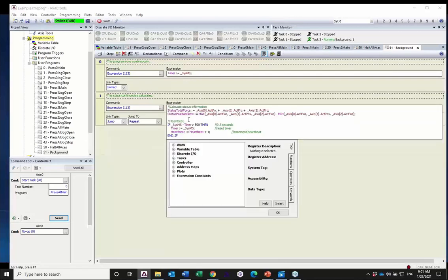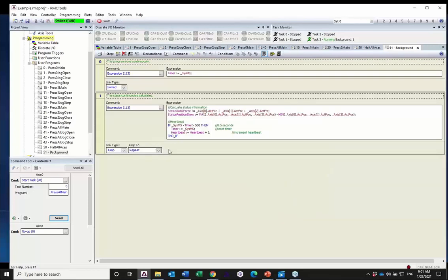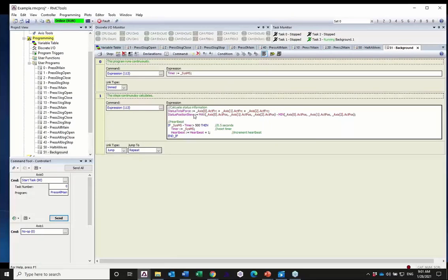So normally, you have to add if-then-elses in the expression to do all that logic where if this happens, then that happens all in one step. It can be a little bit challenging sometimes doing one step. Sometimes we end up doing a state machine inside that step. If you have plenty of tasks, you can actually have multiple programs like this. So maybe one is running all the time, and another one, it doesn't have to run all the time, and so you can do those if-then-elses and kind of take your merry time. So you generally have a choice of which way you can do it like this.